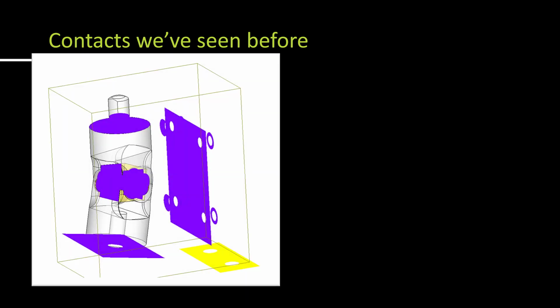So where have we seen contact sets before? If some of you have taken the online training or any training course with SOLIDWORKS, you've probably recognized this cardan joint. I put this picture up because it's a great way to show the surfaces that we can contact with each other in a certain assembly. We can specify no penetration, virtual wall.